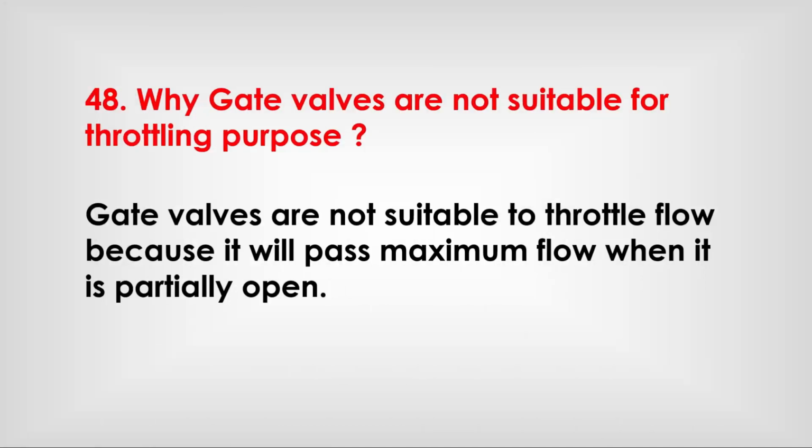Why are gate valves not suitable for throttling purpose? Gate valves are not suitable to throttle flow because it will pass maximum flow when it is partially open.